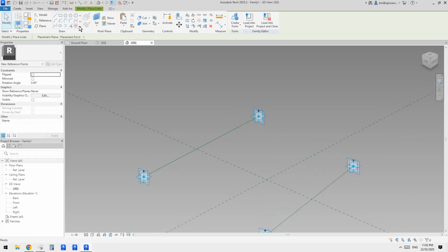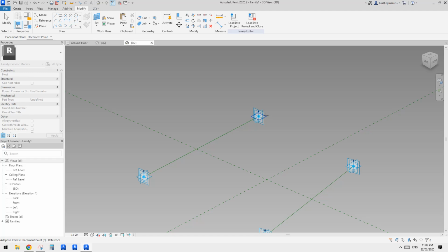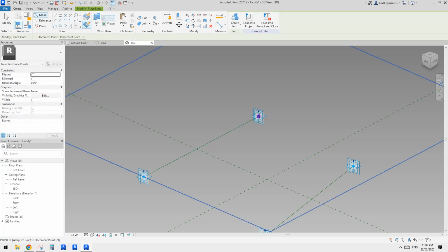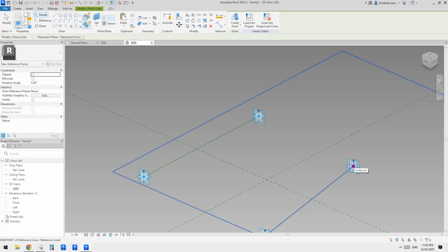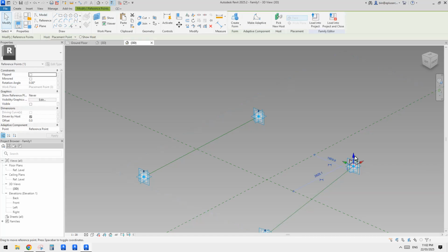So what we're going to do is use a point drawn on work plane, place the horizontal work plane on this point, and place onto point 2. And another one: set work plane onto the horizontal work plane and place it on point 3. Now we select this point, so you can see this is an offset. And this one's offset as well. So we can select both points.